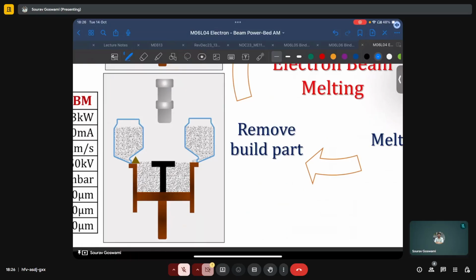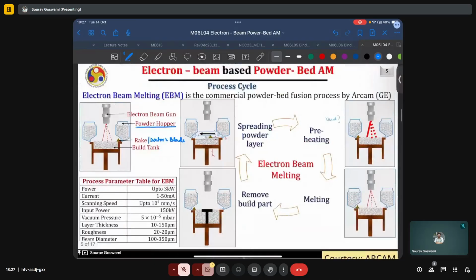For this, the entire build volume containing the printed part and the unused powder along with the print bed will be taken out. This powder will be recovered by suitable means and in all probability will be reused. The part will be separated from the substrate most typically using a bandsaw cutter or a wire EDM, and it can be further post-processed depending on the requirements.